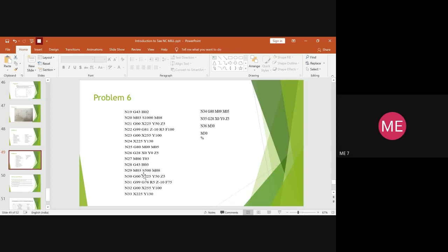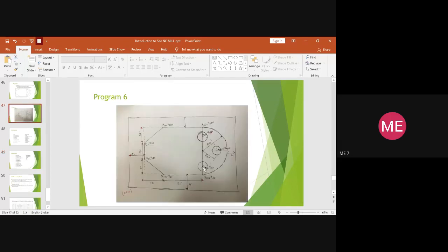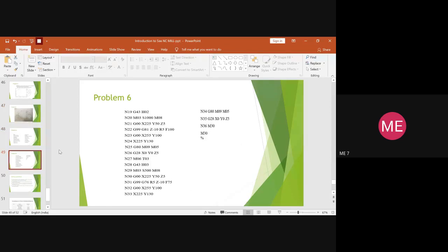Here it is just a finishing operation that we are giving with the boring tool, and hence it's better not to give a high spindle value. It is just 500 which has been assigned. So this will be done. After you provide the spindle speed, again you have to locate the position where you want to start the boring operation. The coordinates of the holes will be the same: this one, this and this. We have identified the coordinates for these 3 positions already.